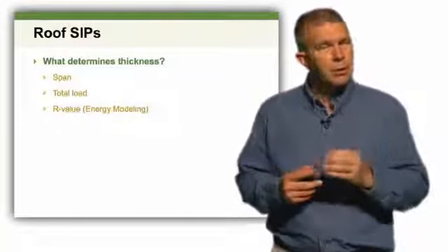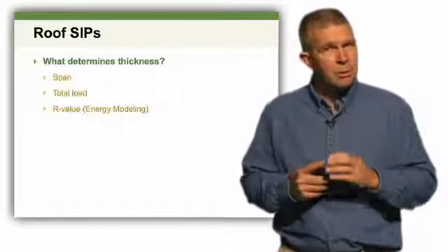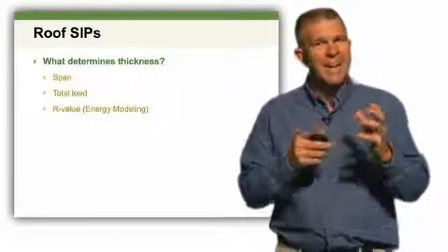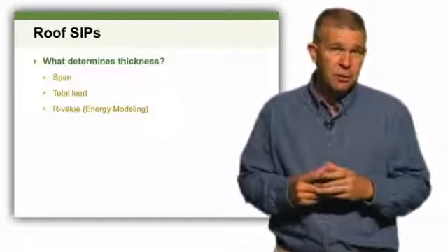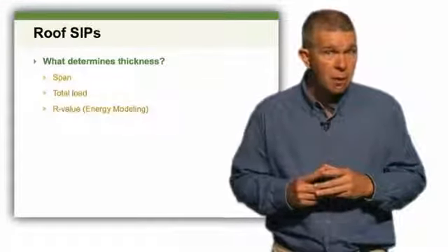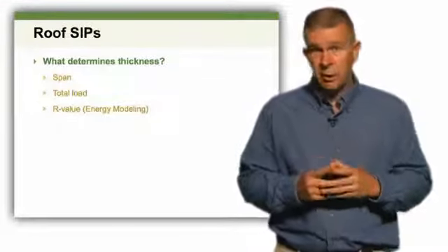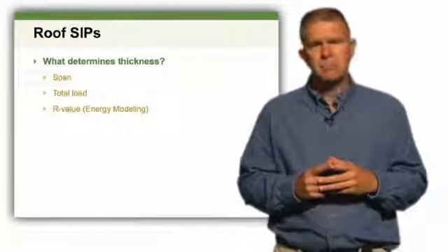So you really need to look very closely at the design of the roof support structure so that you might be able to take advantage of the best possible connection detail that gives not only the homeowner the most energy efficient structure, but allows you to put the project up quicker and perhaps save a few dollars in terms of the engineered lumber components that you didn't have to buy because you didn't need them in those panels.